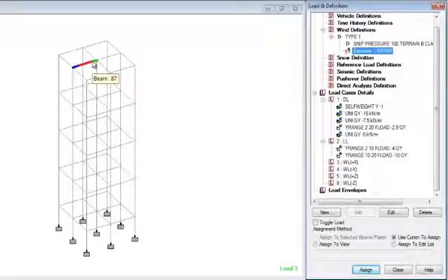The wind flows in four directions. That is why the exposures may also be different for different places. For example, somewhere the wind from the X direction is higher than the wind from the Y direction. So we can add more exposure numbers and give which part will be under which exposure. Let us finish it in this class, and wait for the next class for assigning the wind load.